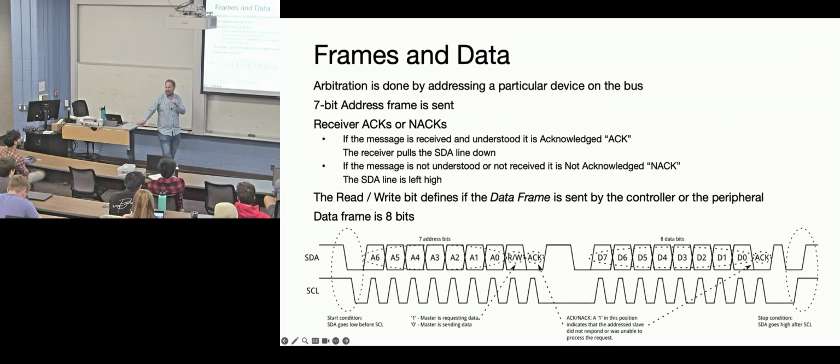Now, the error condition that I was going for, but didn't set you up for any success in figuring out, I realize, is that if there's no device actually connected to the board, this is going to be high. There's nothing to pull it down low, therefore you're going to get a NACK. So it's not uncommon for a student to say, no matter what address I send to it, it always NACKs. And you look at the horrible breadboard, and the wires are everywhere, and it just may not be connected, because a NACK is the same as nothing. Nothing's happening. So you're looking for that NACK.